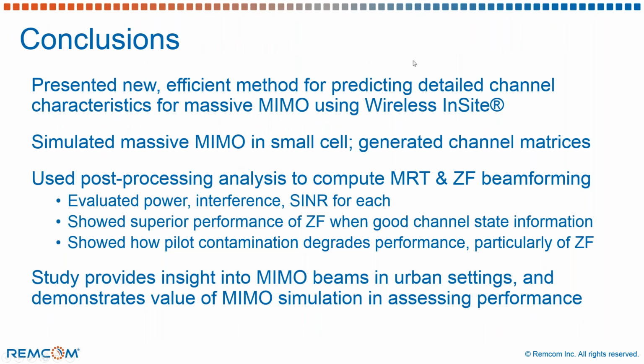So in conclusion, we've presented a new and efficient method for predicting detailed channel characteristics for massive MIMO using our new Wireless InSite MIMO capability. We simulated massive MIMO in a small cell, and we generated channel matrices from our simulations. We then used post-processing analysis to compute maximum ratio transmission and zero forcing beamforming, and we showed results from our calculations of power, interference, and SINR.